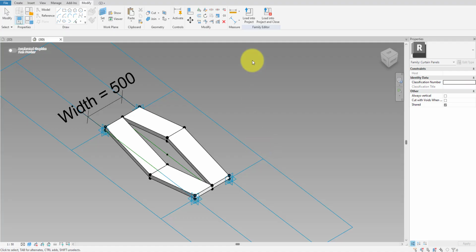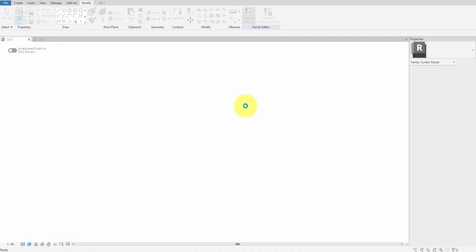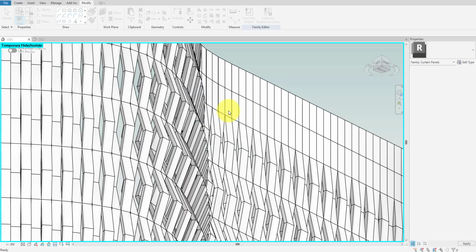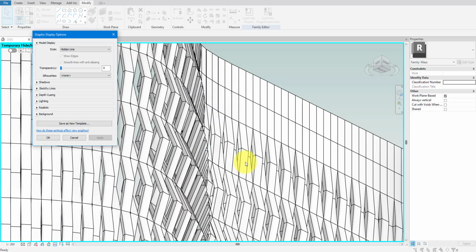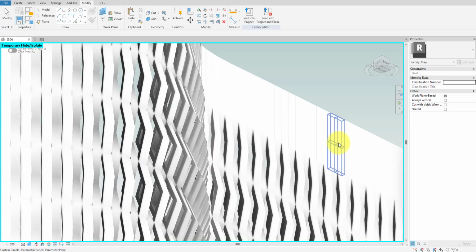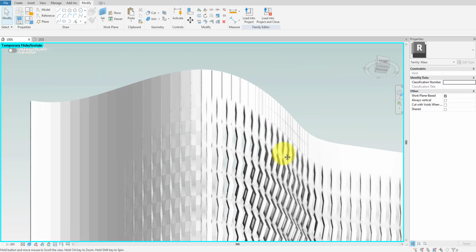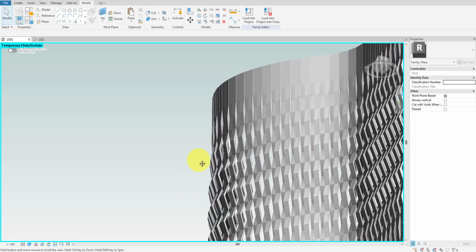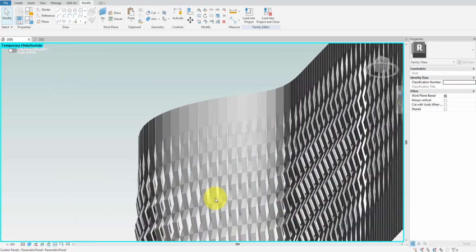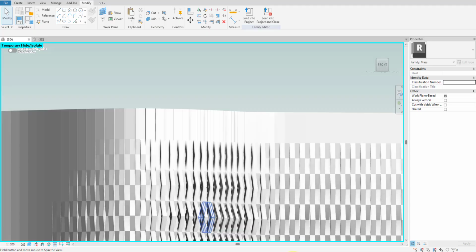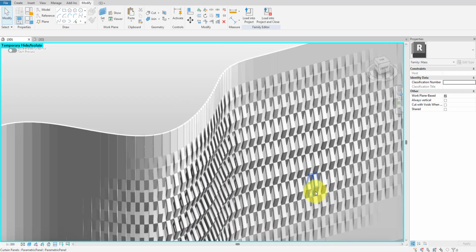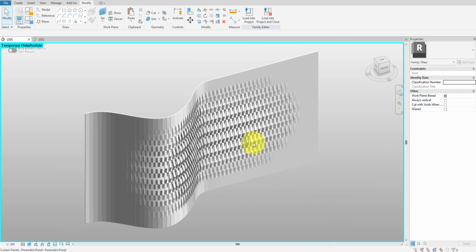At least that looks better than the dull grey one we currently have. I can now load the family back to the mass and select to overwrite all parameters. And there we go. The facade looks a lot more modern and clean already. Moving on, we need to place this mass inside a project model. After all, this is still just a conceptual mass family, so we can't annotate or schedule the panels in here. We need them in a project model to do that.